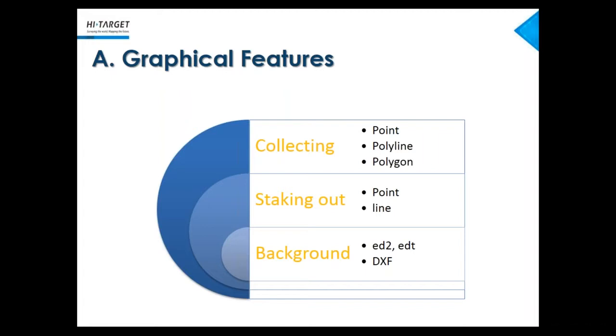For the background, we support data formats like ED2, EDT, which are the data formats coming from HiQ GIS, our GIS data format. So that means you can import the satellite image or the GIS vector data for your reference, or you can import DXF data and use that as a background.